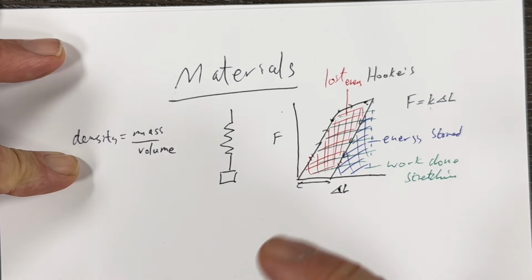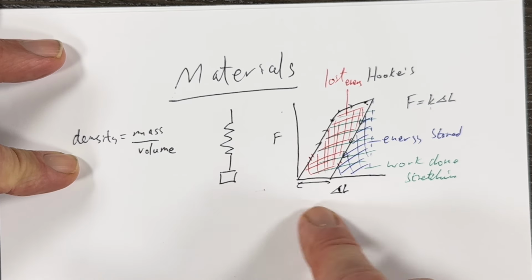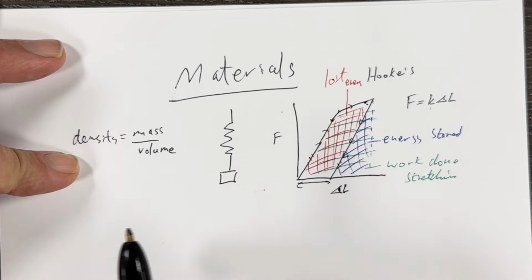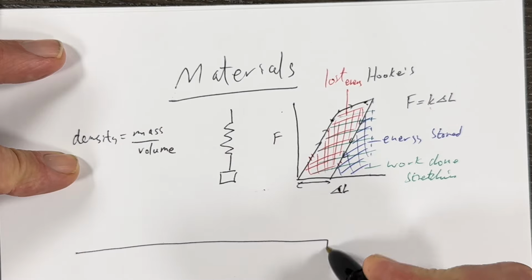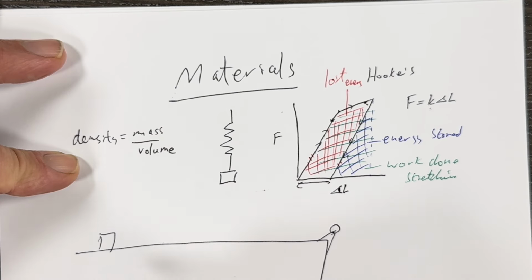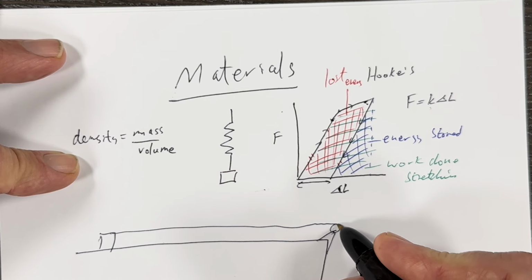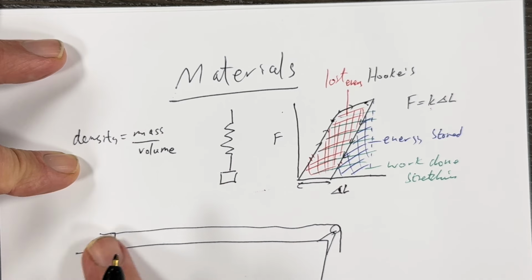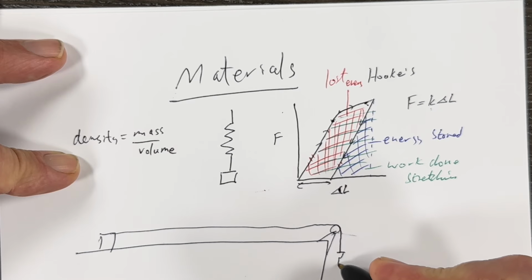And then from there, we're going to come back to this graph and look how it would be different if we were talking about stress and strain, but that's kind of getting ahead of ourselves. This is an object. Then the next thing we did was to think about finding the equivalent properties for the material, not on an individual object. So if you remember, we clamped a wire down, a long thin wire, it has to be long to get enough extension, a pulley on the end, a way of adjusting the load, maybe a mat underneath to keep the floor safe,